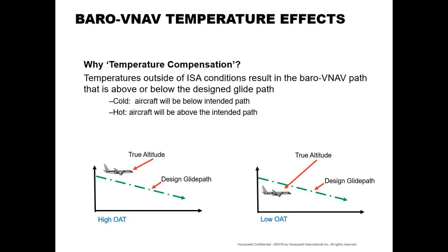So why is it so important to compensate for altitude when extreme temperatures exist at airports? Since approaches are charted based largely on obstruction clearance, pilots must always know where they are in relation to required altitude constraints along an approach. Aircraft operating closer to the ground can present a concern for obstacle clearance. A barometric altitude reading can be affected by extreme temperatures.